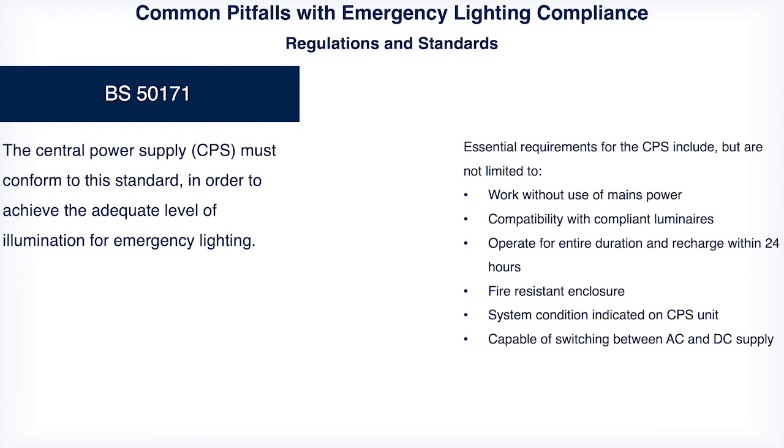The next standard, BS EN 50171, is all about central power battery systems, CPS for short. And the BS EN 50171 really specifies the general requirements for these battery supply systems. It's an independent, separate energy supply rather than having localized battery and converter units within the luminaires. And so the network of emergency lighting products are permanently connected to AC supply voltage not exceeding 1,000 volts, and use those as an alternative power supply.